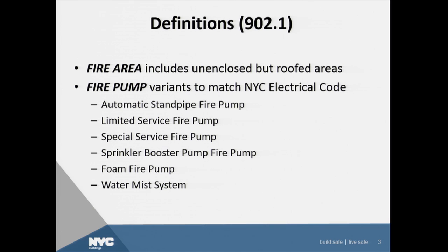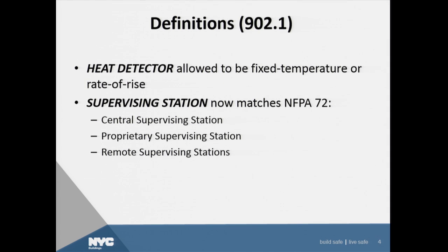The term fire pump now matches the electrical code, with respect to an automatic standpipe fire pump, a limited service fire pump, et cetera. For those of you who are fire protection engineers, that may be more important than others. Okay, so the heat detector now makes it clear that the activation can be a fixed temperature or a rate of rise. And that's important when you're talking about different types of environments where you need to select the right kind of detector so you avoid those false alarms.